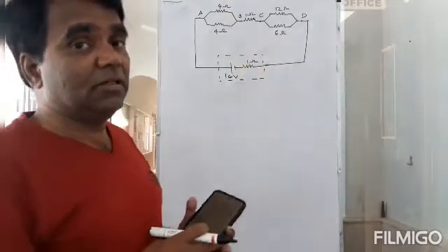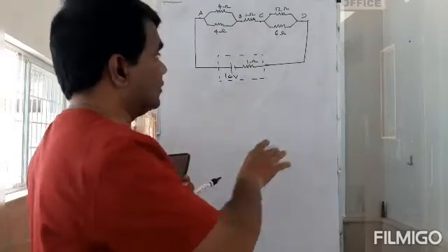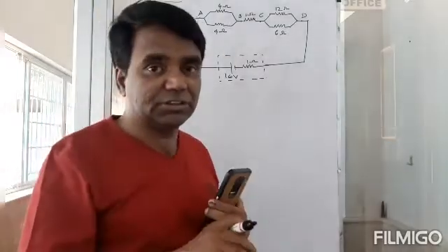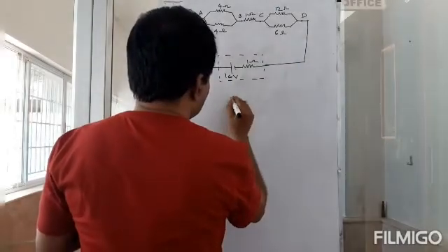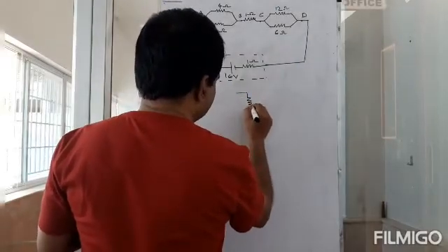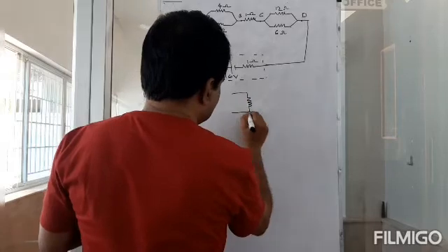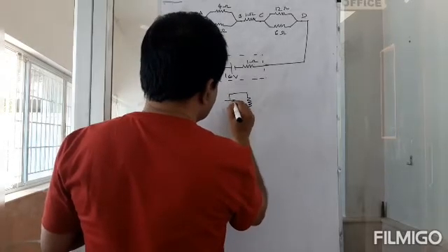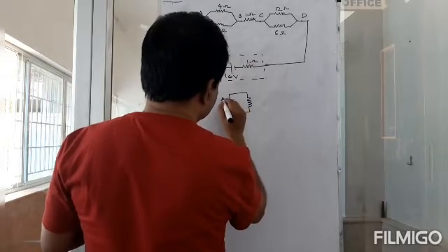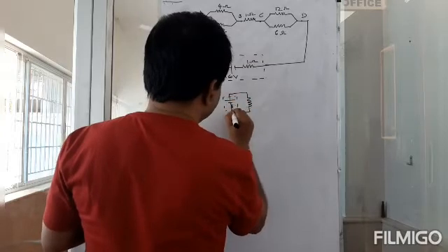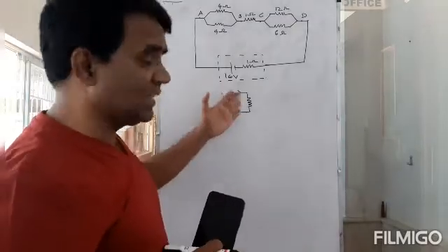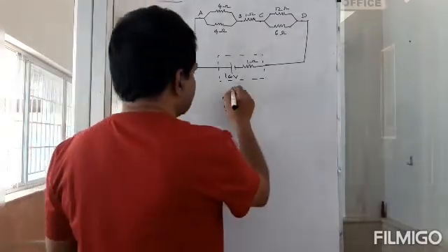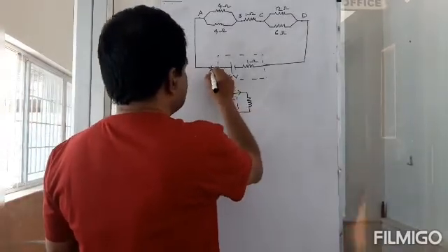battery. Okay? Because you see, what is the objective of finding an equivalent resistance? It is this, right? I want to replace the entire circuit with a single resistor, and then I want to connect it to the same battery, right? Then if I did that, then this must be sending the same current I as it was sending here.